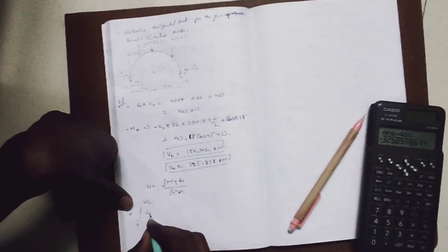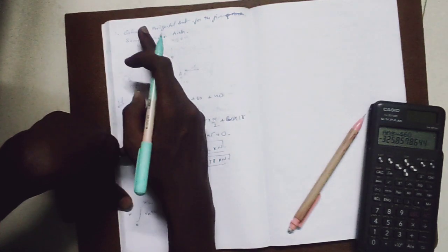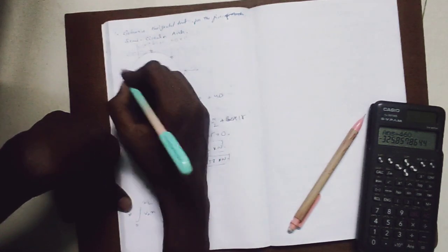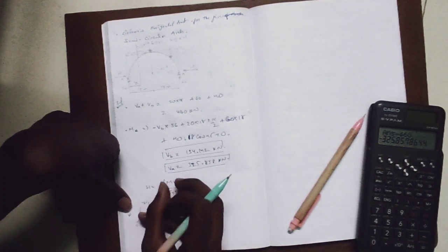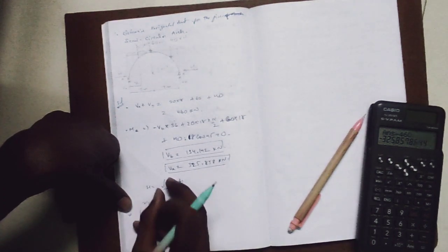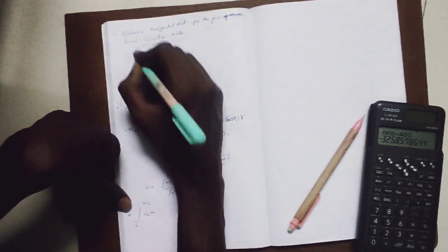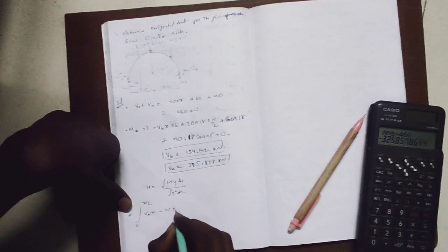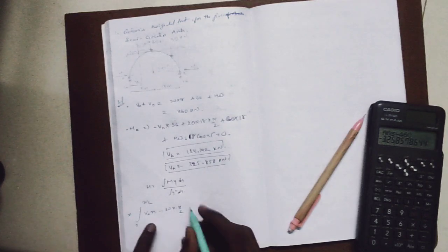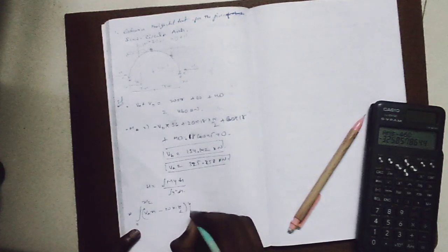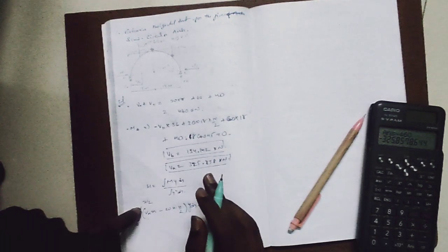So VA into x, in clockwise direction. We will not consider the horizontal reactions in this formula, as we have to find horizontal thrust. So we will consider this 20 kilonewtons, minus 20 into x by 2, right? We don't have any extra forces acting over there. So into y ds. So we have found till pi by 2.